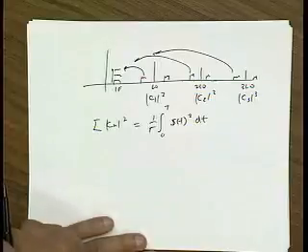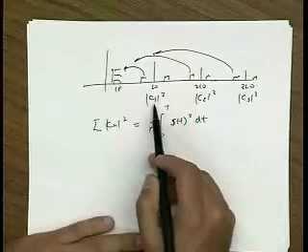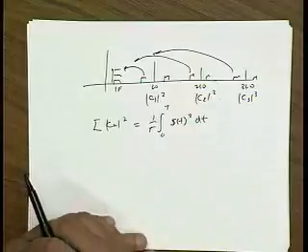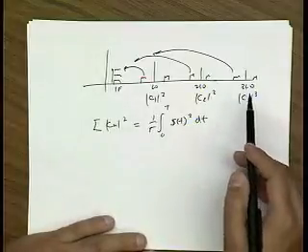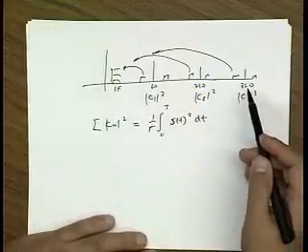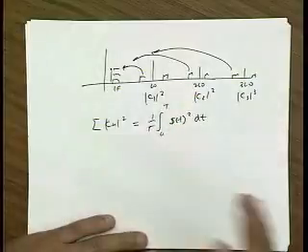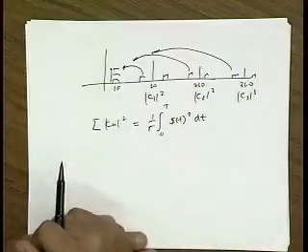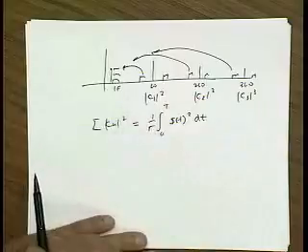Okay? And you can actually calculate what's the noise contribution from second compared to first, right? So if it's a square wave, the first contribution would be from the third harmonic, right? And that is down by a factor of 1/9. It's 1/3 squared. So you see the noise contribution is about 10%. And that's the biggest contribution. Then you add the fifth. That's down by a factor of 1/25. So this converges pretty quickly for most switching waveforms.